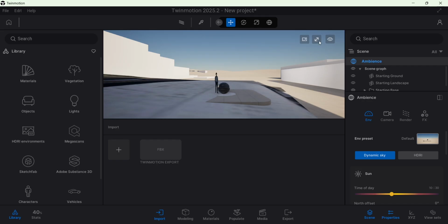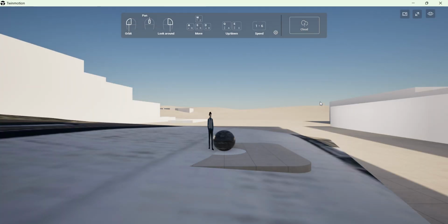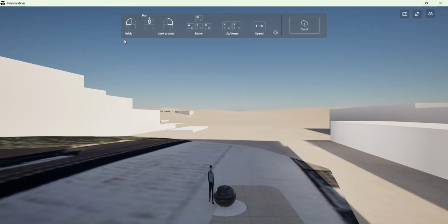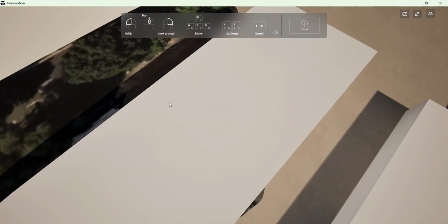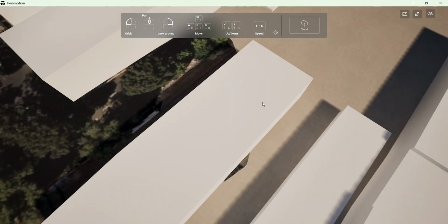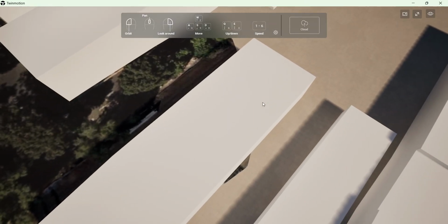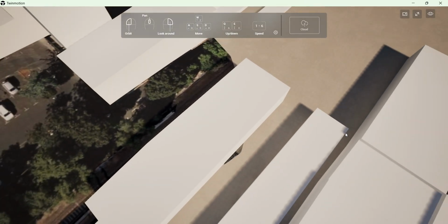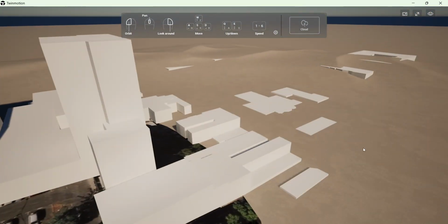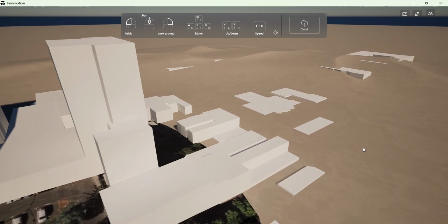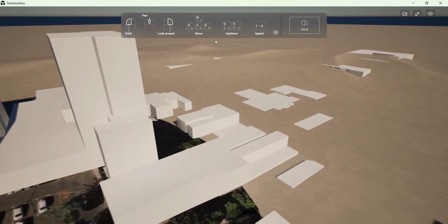And here we go. This screen here basically shows the 3D scene. I'm going to use this button here in the middle of the top right hand icons to just open this up. And this basically just gives us our 3D view. So the controls are up on the top panel here. So left click is just orbiting around a pivot. The pan, zooming in and out, is just the center scroll on your mouse. To look around, it's right click, and similar to any other game, using your WASD keys you can move around, also your Q and E to move directly vertically